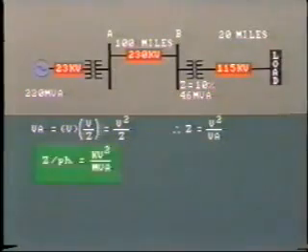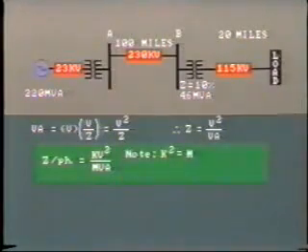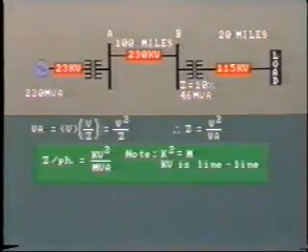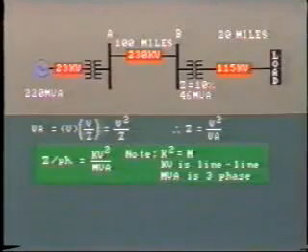In terms of the power system, impedance per phase equals kV squared divided by MVA. In this expression, the kV and MVA units are quite compatible because we are squaring the kV and so bringing another 3 zeros into the top line. And by using line-to-line voltage, we get impedance per phase. The MVA value is total three-phase. Verify these units using your workbook.